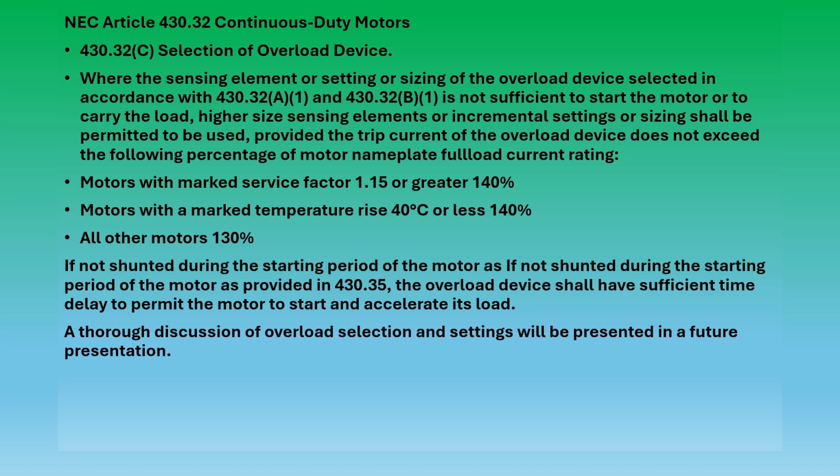If not shunted during the starting period of the motor as provided in 430.35, the overload device shall have sufficient time delay to permit the motor to start and accelerate. A thorough discussion of overload selection and settings shall be presented in a future presentation. So yes, you can increase the overload size up to 140% for a service factor of 1.15.